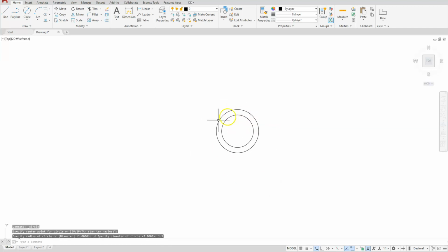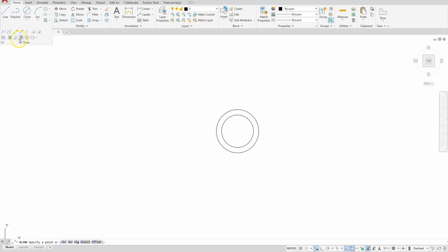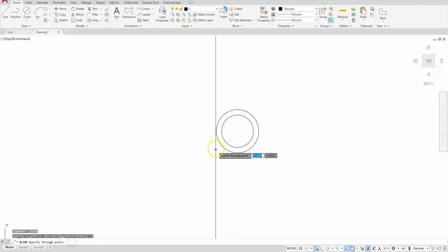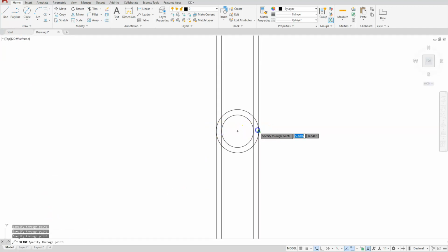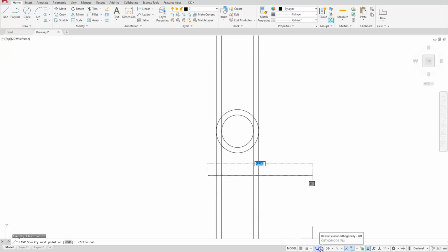This is about as much as I can draw on my top view, but I can use this to keep things in line with the bottom view that I'm going to create, or the front view in this case. So let's go ahead and switch on over and use construction lines, vertical. And let's go ahead and click at each one of these quadrants. Next, I'll create a horizontal line just anywhere below this one, but I will try to leave enough space because I have a dimension that I have to put there. So I'm just going to draw a line going right across this, and I want it to be horizontal. So make sure you turn your ortho on. Click here and place it.